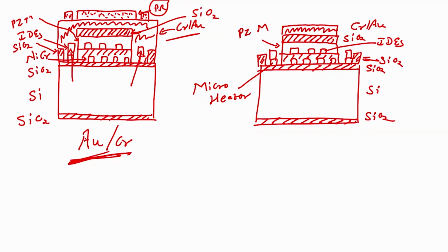You can draw a schematic similar to schematic 1. When you perform lithography, you can mask the area with the help of photoresist, so that when you dip the wafer in chrome and gold etchant, the chrome and gold will get etched only in the region which is not protected by photoresist.